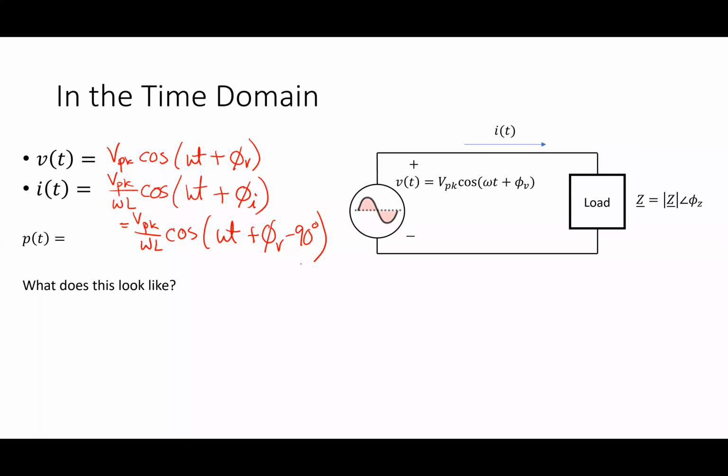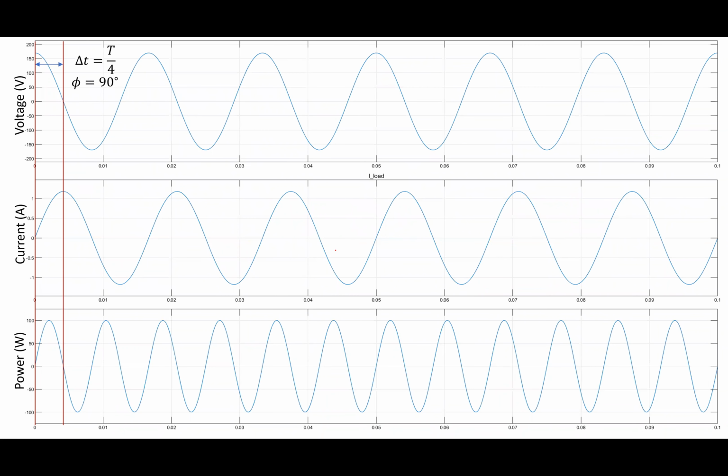What does that voltage and current look like if I were to show them? How would they relate to each other? Yeah, cosine and sine. If phi V was 0, there'd be this cosine-sine relationship. There's a 90-degree shift between them. If I have a negative 90 here, which direction am I going? To the right. Yes. So there's my voltage. My voltage is cosine. My current becomes sine. They're shifted, or out of phase, by 90 degrees, or a quarter of a period.